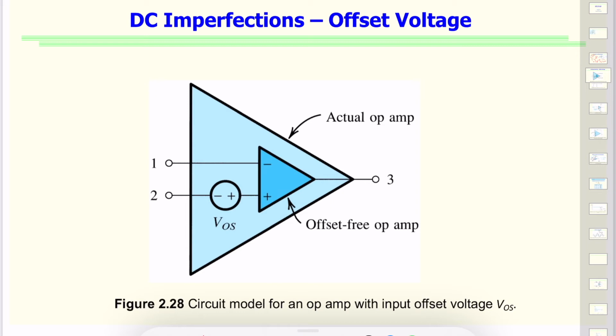If you think about it, there is a problem with an op-amp. Even if you tie the two inputs together and ground them, we would still get a signal on the output. So despite zero differential signal, some finite voltage exists.